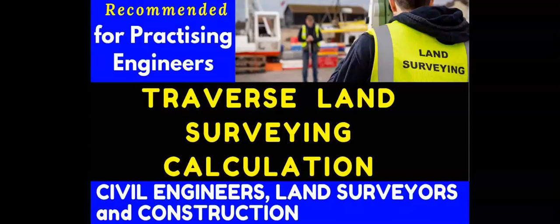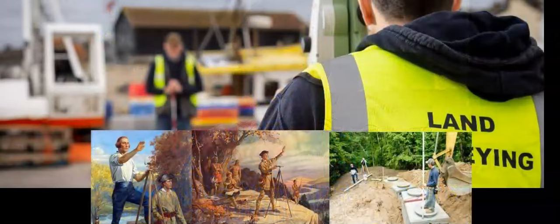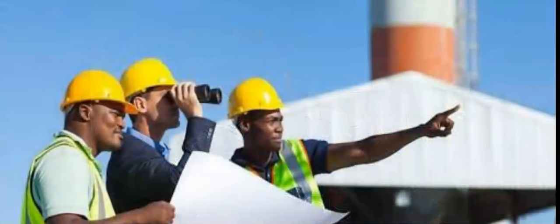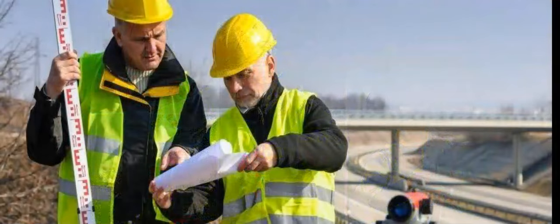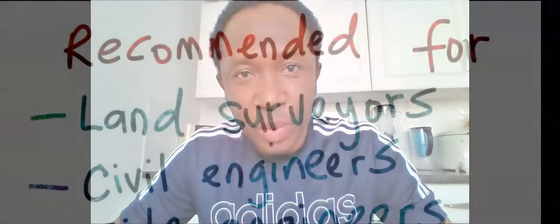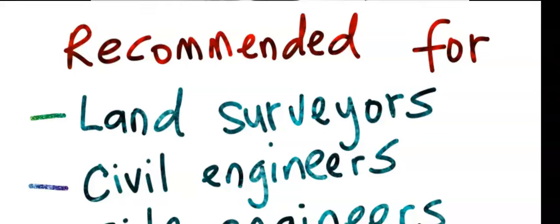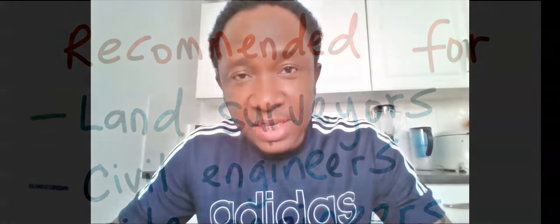In this video, we are going to learn traverse calculations in civil engineering and construction. In construction field surveying, traverse stations are used to establish points and lines for control networks. Construction traverse surveying can be open traverse, like in road and railway network. It can be closed, like in fences and building construction.